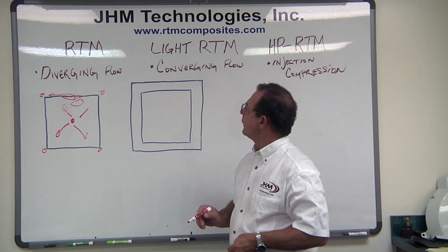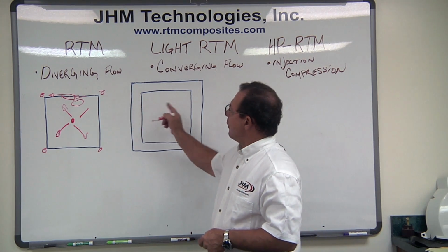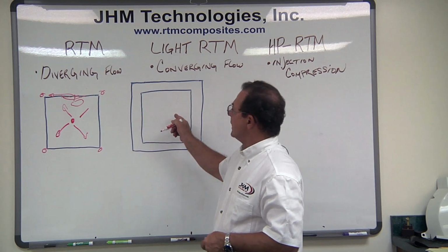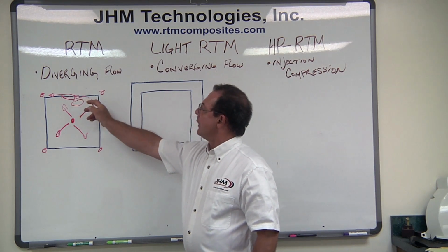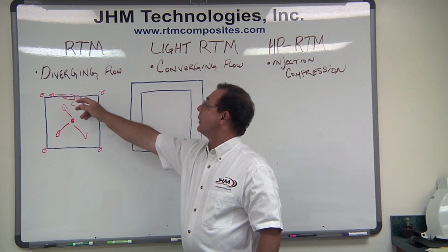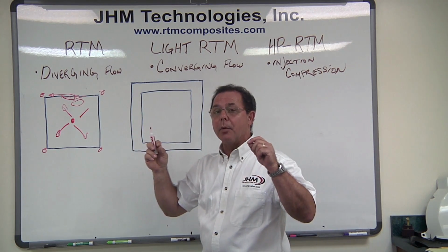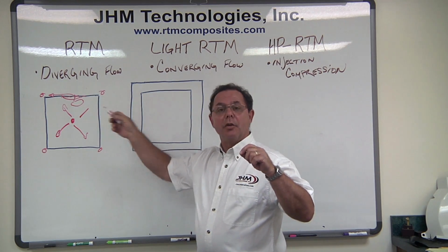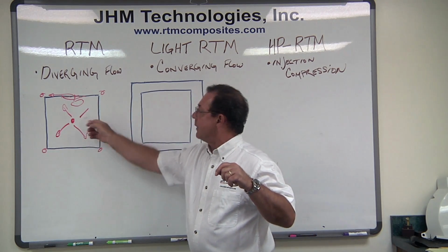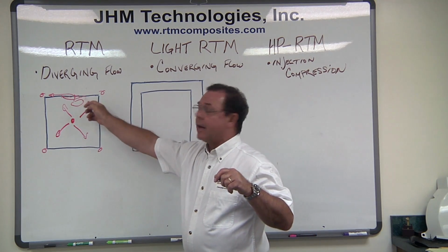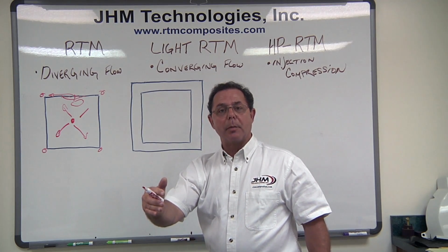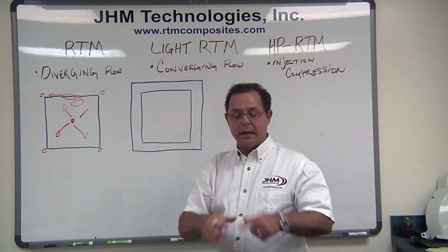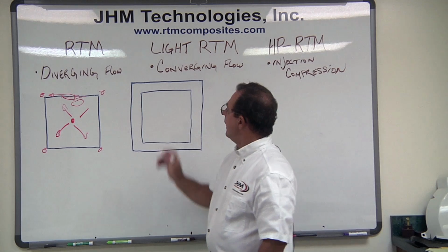So what is the difference? Well, again, if we were molding that same square in a light RTM tool, the interesting thing here is, when I go back and I discuss this, what we're pinching or concerning ourselves to pinch that edge of fiber, because that, when you're running production in a mold design of this configuration, that'll cause you more scrap than anything. That is resin racetracking around the fiber pack and getting to a vent, and not then filling that void.